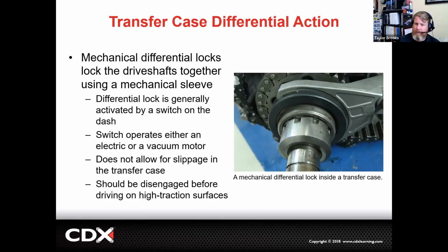When we use this shifter, oftentimes if we're shifting it into a lock situation, we're usually having to shift it into four low and then hitting a button or a solenoid to engage that lock. In some situations, the shifter gets moved up or pushed down to engage that locking mechanism as well. You can see the lock mechanism here on this shift fork, where there actually is a set of teeth that are going to engage into that drive assembly when the shifter is selected correctly.